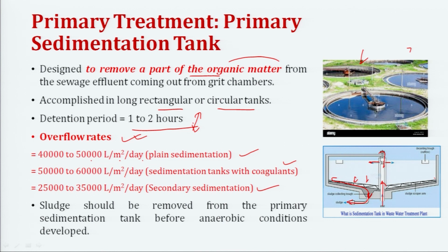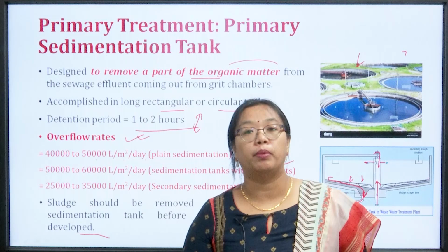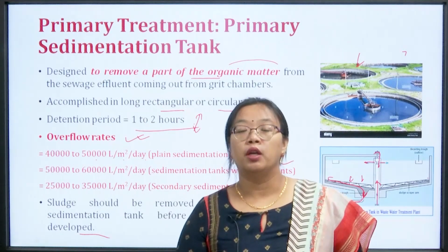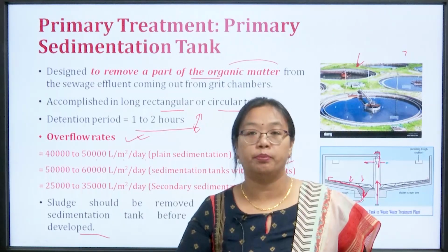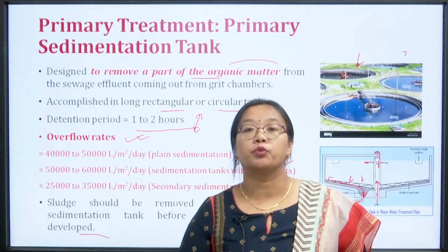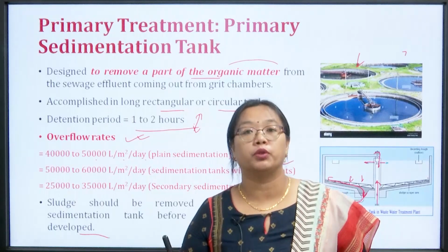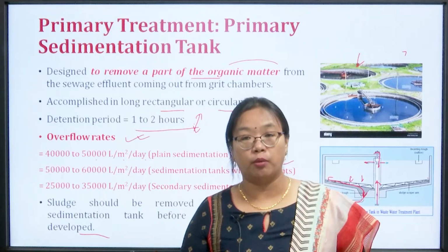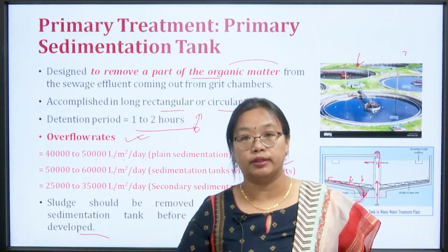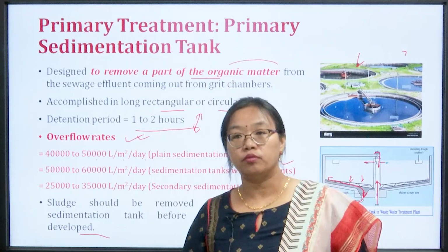Sludge should be removed from the sedimentation tank before anaerobic conditions develop, because if anaerobic conditions develop, we may have other huge problems, like very bad, foul smells. The principle is the same as in water treatment, but here we are using wastewater, so obviously the sludge amount is going to be huge. In water tanks, whatever settles is lesser; here it is going to be more.